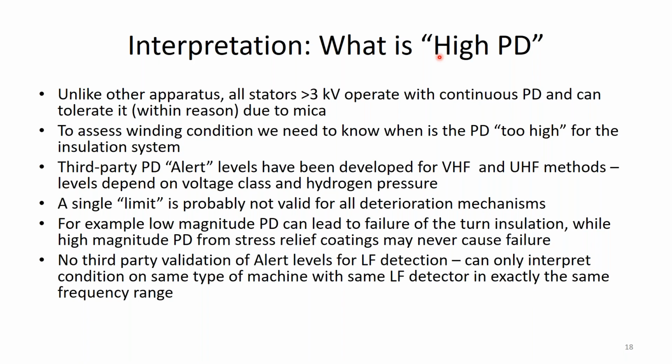Something that I'm going to address a little bit later: these limits, although our guidance that I'll show you on the next page shows limits that encompass all failure processes within the stator winding, in reality, I know that's not true. I need separate limits for different insulation aging mechanisms.